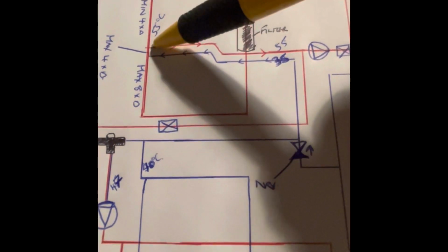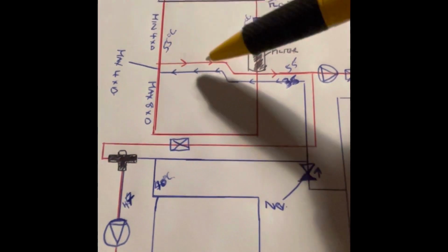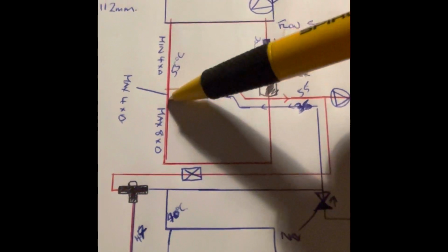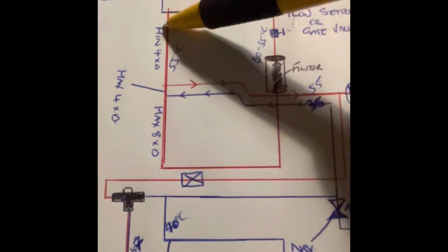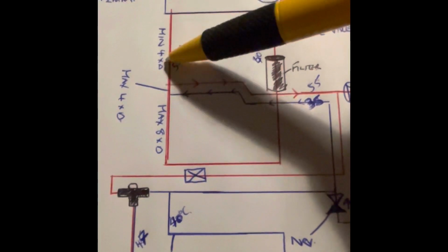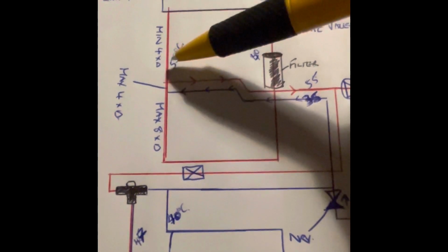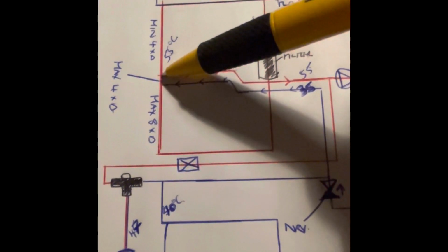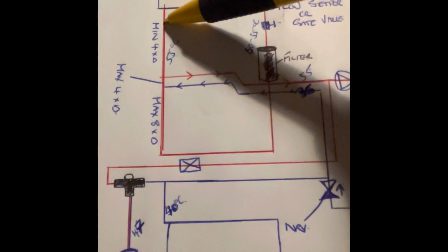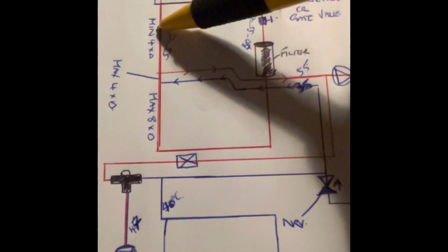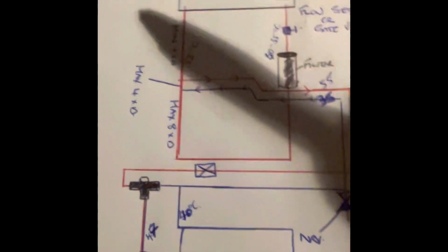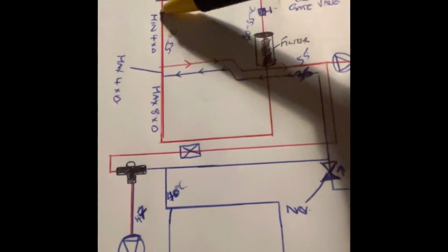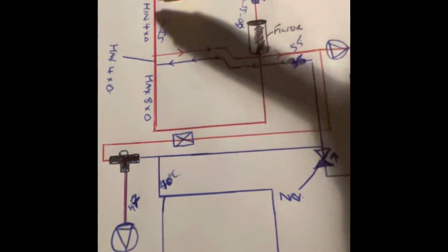Off that, we've got some closely spaced T's, closely coupled T's, or CCTs. And those are specifically spaced T's in a position of, on the flow going into it, a minimum of 4 times D. D is the diameter of the pipe that you're using. So from that T to your first elbow, you need a minimum of 4 times D, which is 112mm. So straight out of my boiler, I need a minimum of 112mm before a bend.